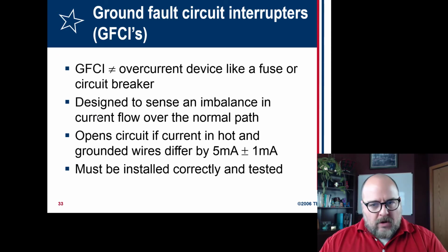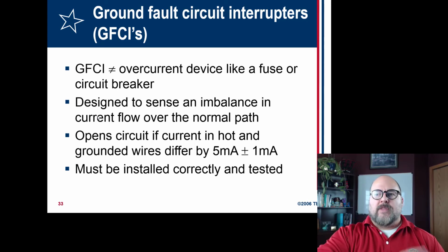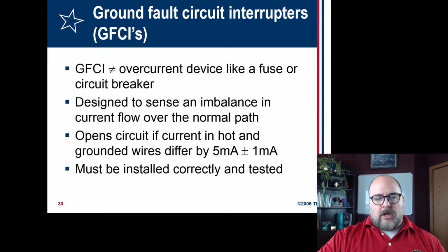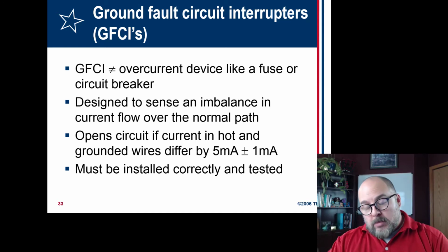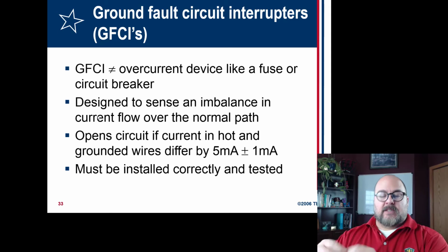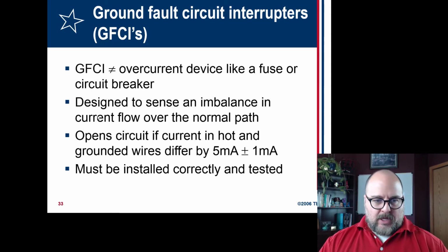GFCI is not an overcurrent device, such as a fuse or a circuit breaker. GFCI is for when there is a slight differential, whereas the overcurrent device is designed so that if you're trying to draw too much through that device, it shuts off and kills the circuit, stops delivering power to it.